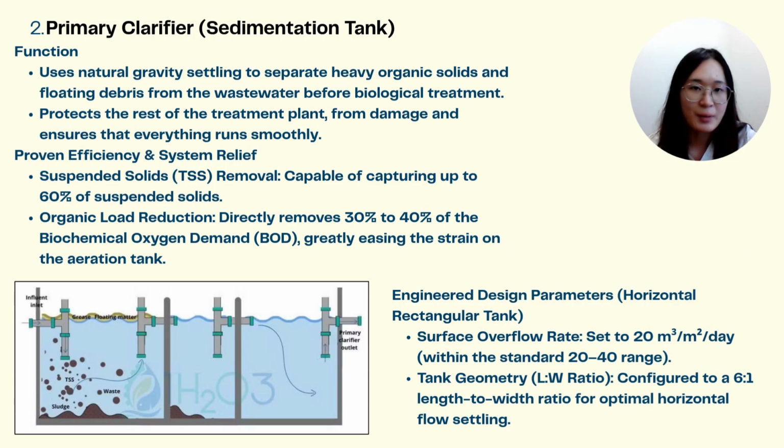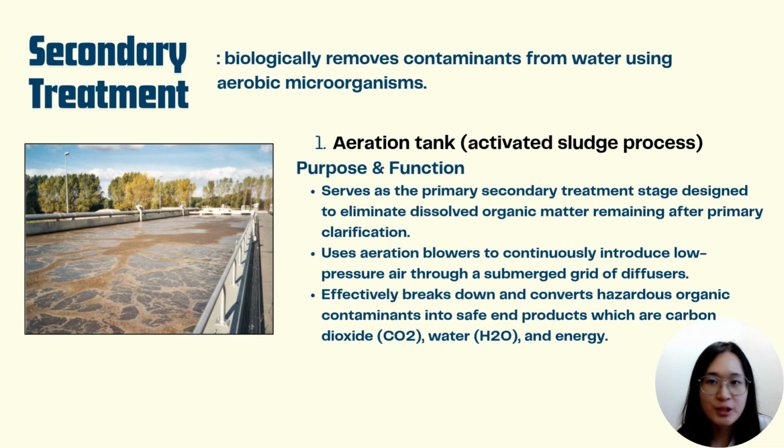And for the design parameters, we set 20 cubic meters per square meter per day for our surface overflow rate. And for the tank geometry, we configure a 6 to 1 length to width ratio for optimal horizontal flow settling. Now let us move on to secondary treatment.